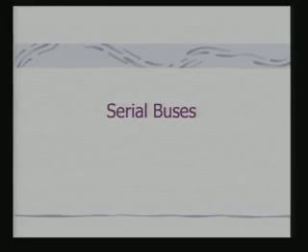Next, we shall look at serial buses. In fact, when we have looked at this SOC and PCB based application, this whole concept of the buses had been parallel data transfers. If we are transferring 32-bit, I shall be transferring that on parallel lines. Obviously, this can be used for short distances, that is, within chip or within card.